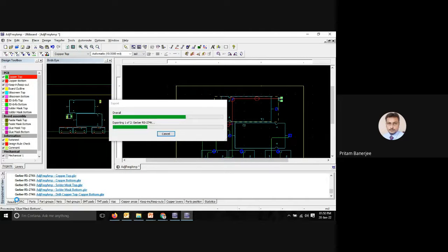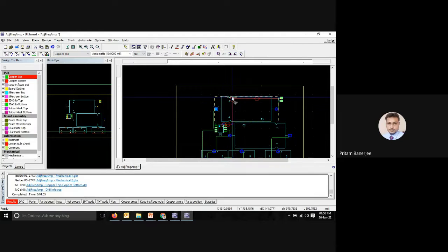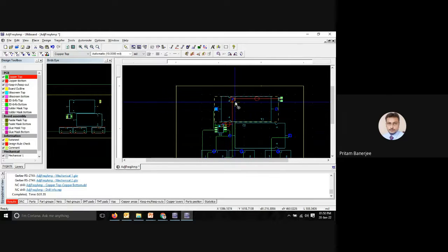Ignore errors, because it was checking the DRC, and as I have swapped the connectivity layer, I may not have fulfilled the design rules. It will be giving you whether you are actually following the design rules or not. It is showing that this net is containing only one pin. That means one pin is attached, but another pin is not attached with the connectivity. So you need to correct those design rule checks as well.